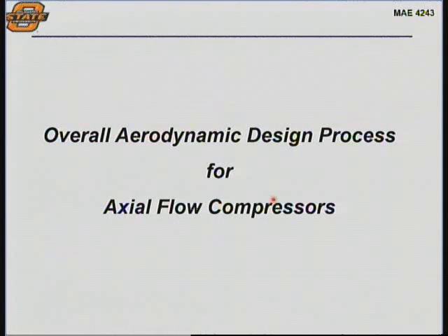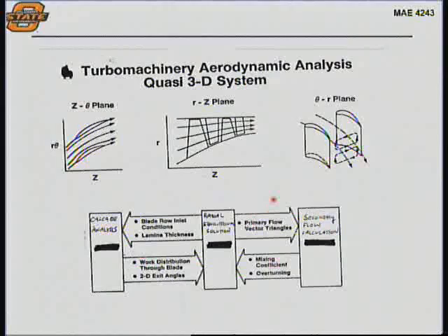So the design process that's been used for many, many years is still a quasi three-dimensional system. Think of the axial flow compressor geometry in cylindrical coordinates, right? If you look at it in the RZ plane, you're looking at this side flow path view. If you look at it in the theta R plane, we're looking at flow in the side-to-side or circumferential direction.